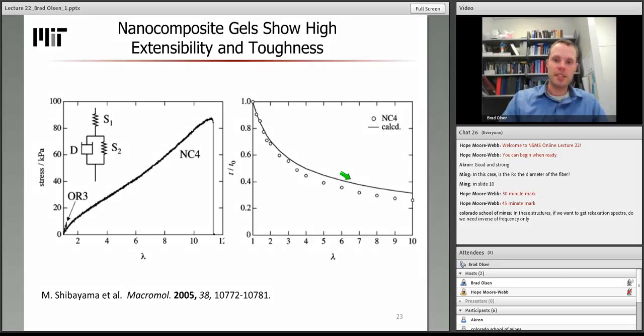And this is traditional for polymer network type materials, although for hydrogels in particular, because you can have solvent transfer in and out of the material, essentially poroelastic effects during deformation, volume conservation is not necessarily held in all hydrogel materials.